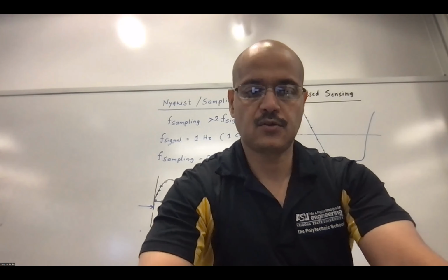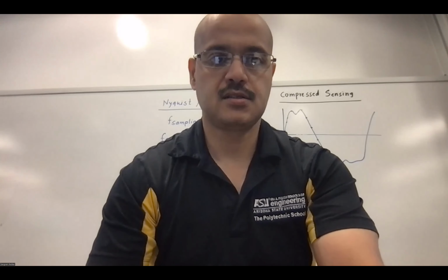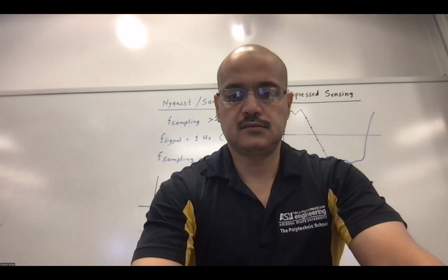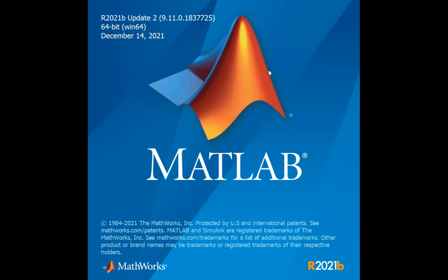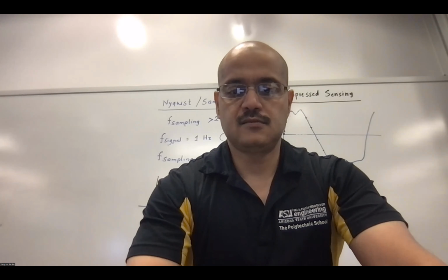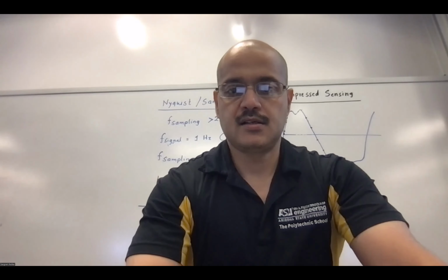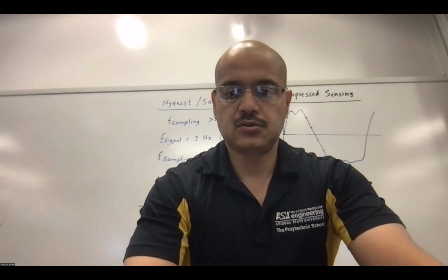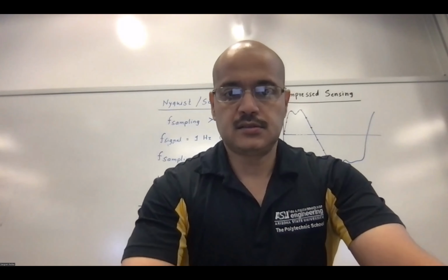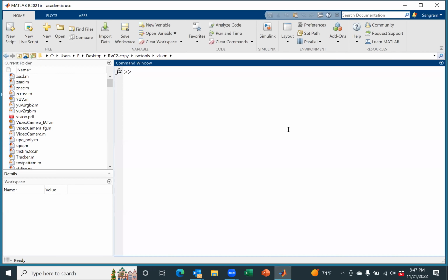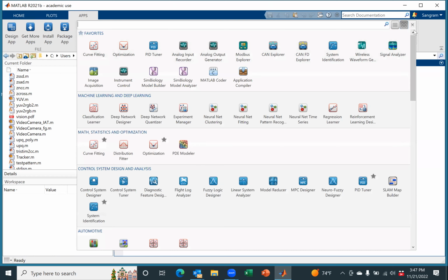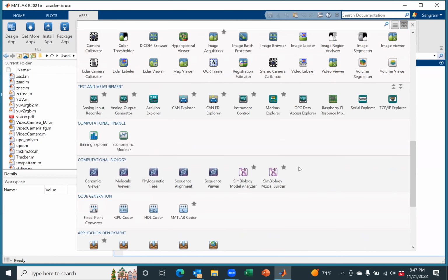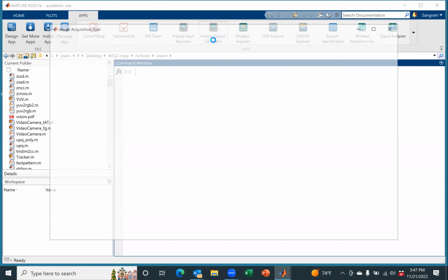So basically go to MATLAB and now go back to apps and then go to the image processing, image acquisition, and now let's hope that it captures.